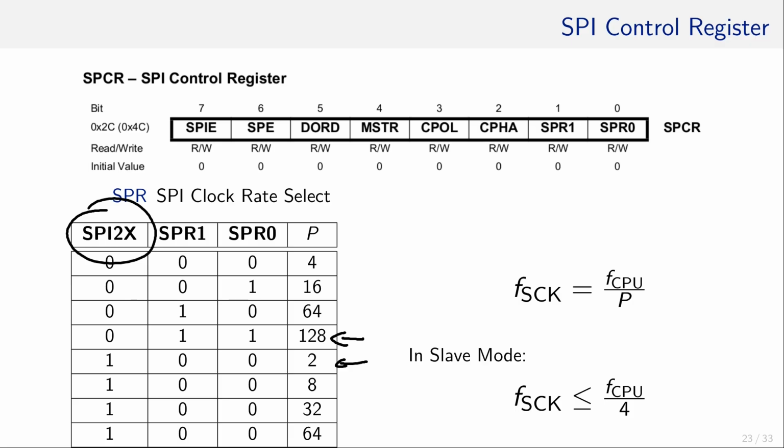One important note on the side. In case the ATmega328P is to act as a slave, the frequency of the SCK wire needs to be equal or lesser than a quarter of the system clock to guarantee the data transfer. It might run at faster speeds, but errors might also occur. Since the Arduino currently runs on 16 MHz, the maximum frequency is therefore 4 MHz for SPI.